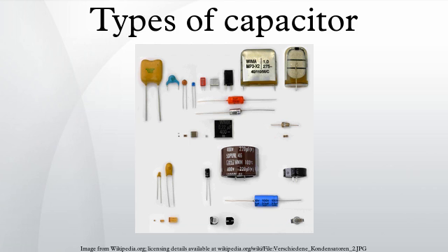A key advantage of every film capacitor's internal construction is direct contact to the electrodes on both ends of the winding. This contact keeps all current paths very short. The design behaves like a large number of individual capacitors connected in parallel, thus reducing the internal ohmic losses and ESL. The inherent geometry of film capacitor structure results in low ohmic losses and a low parasitic inductance, which makes them suitable for applications with high surge currents and for AC power applications, or for applications at higher frequencies.